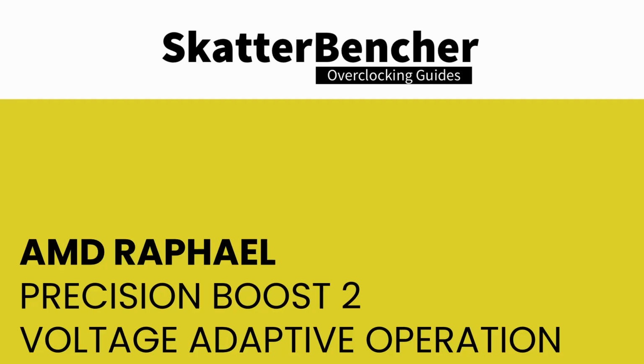Despite having these really advanced technologies like AVFS, or the part-specific voltage frequency table, or the tester to platform voltage offset and boot time calibration, AMD can still not exactly predict what will happen in the real world. Sometimes the transient conditions are so rough that the jump from idle to load or load to idle causes the voltage to drop too much, and that would result in a system crash.